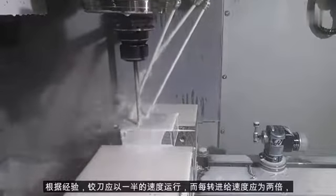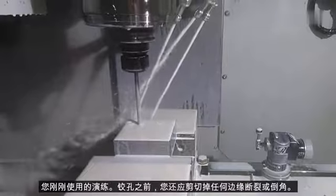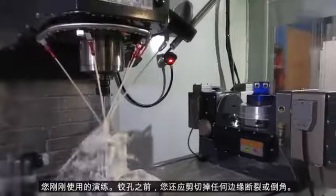As a rule of thumb, you should run a reamer at half the speed and twice the feed per rev of the drill you just used. You should also cut any edge break or chamfer before reaming.